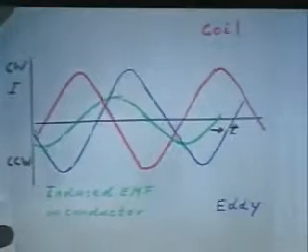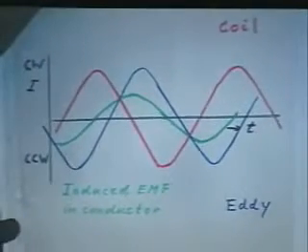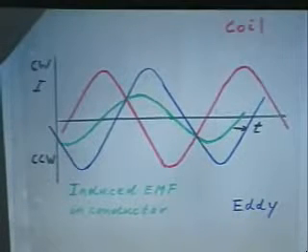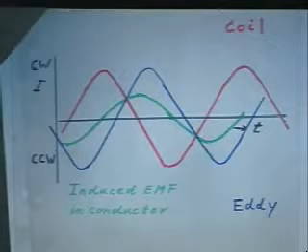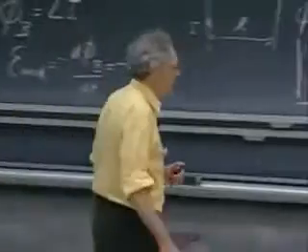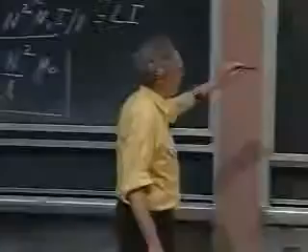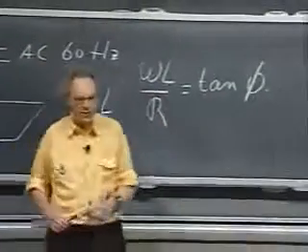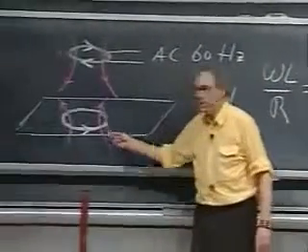Now, in the case when we levitated the woman, I'm sure that the phase delay was not 90 degrees, but maybe it was only 30 or 40 degrees. But the net result is, even though the shift is not 90 degrees, that you get, on average, a repelling force. And so the secret of the repelling force in the case of the levitation of this coil, and therefore of the levitation of the woman, lies in the fact that there is a finite self-inductance in here.